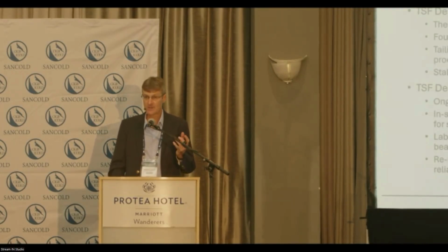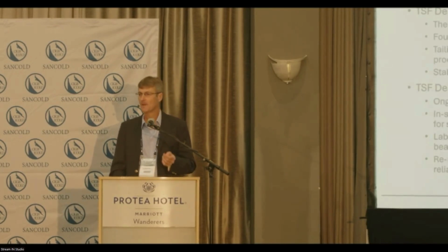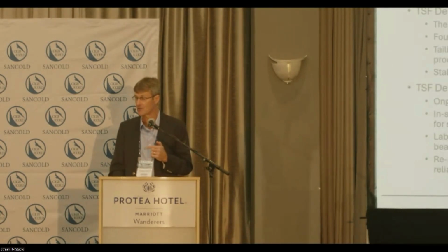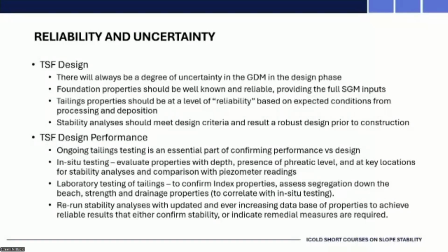And yes, if it's not a fantastic range of samples that you've got up front, during the performance stage, during the construction phase of the tailings dam, you've got the opportunity to keep testing, keep gaining knowledge, keep building that database. And that comes later. So obviously your stability analyses up front for design, that's what you've got. You've got the information you've got, you do the best you can with that information, but you've got to keep checking that during the operational phase.